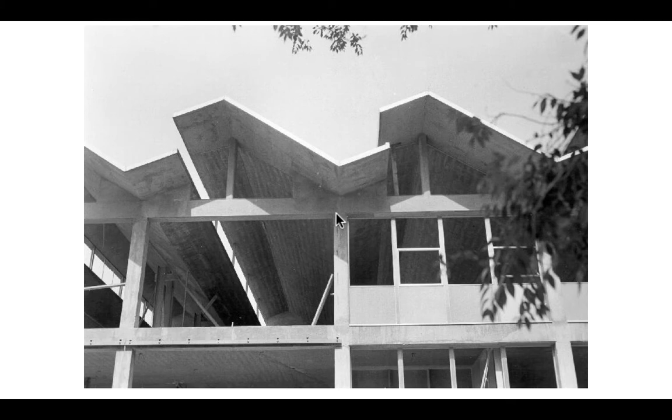It is spanning from column to column, so it's got a structural function. It's keeping the rain off of that space, right? It's functioning as a roof. This area is not only functioning as the tensile flange, right, the bottom flange of the I-beam. It's also functioning as a gutter to take rainwater off and over the edge of the building. And you can see here the gap between the kind of low flange of this folded plate and the top or compression flange of this folded plate. There's a gap there that allows them to bring in daylight.